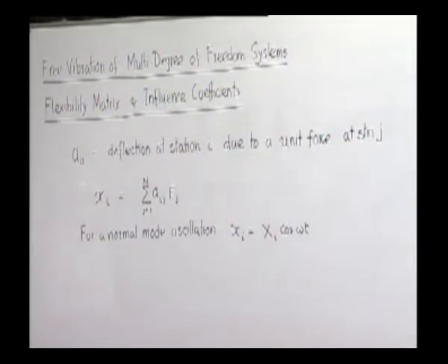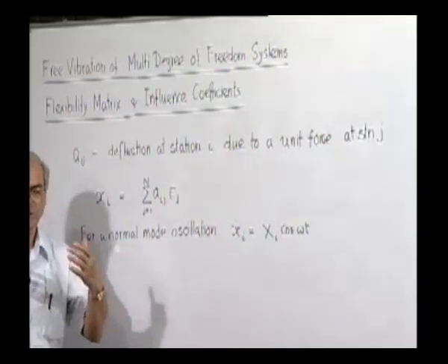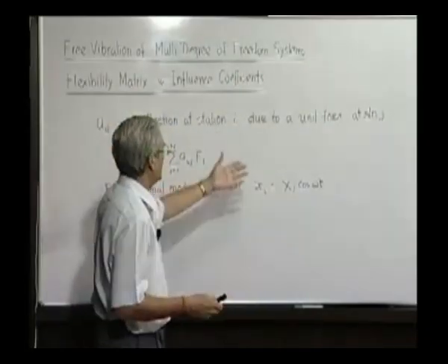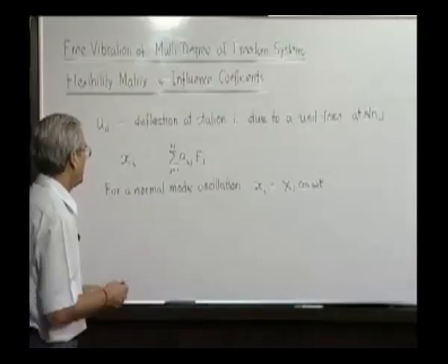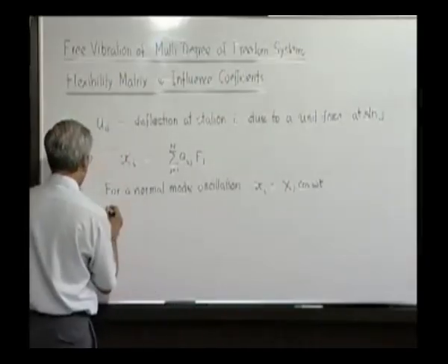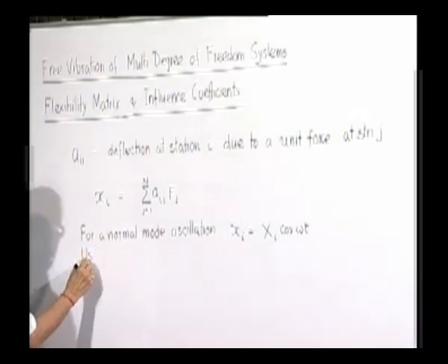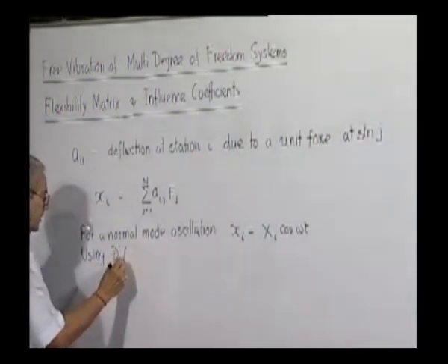Now the question is that when such a vibration takes place, what will be the forces acting? How do you convert? As a static problem, you can see it is very simple, but a dynamic problem, we have to convert to a static problem by applying D'Alembert's law or D'Alembert's principle. That we have done earlier also.